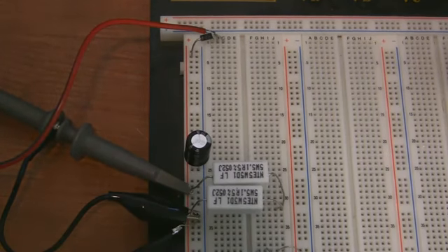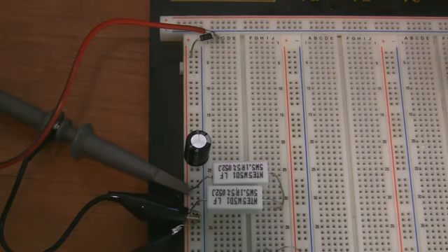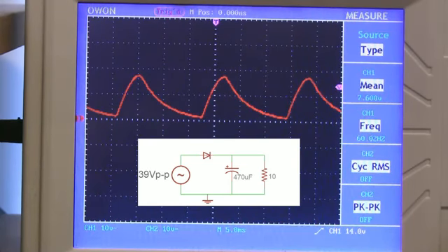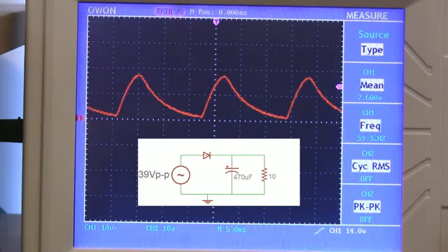With a 10 ohm load, this circuit should draw a lot more current. Well, that sucks. Now we're back to the situation where the voltage is sagging in every cycle. The average voltage is 8 volts, so we're only drawing about 0.8 amps, and the magnitude of the voltage ripple is just huge. Imagine trying to power something with this. The voltage would constantly drop so low it would never even stay on. So even 470 microfarads is just not cutting it anymore as an energy reservoir.